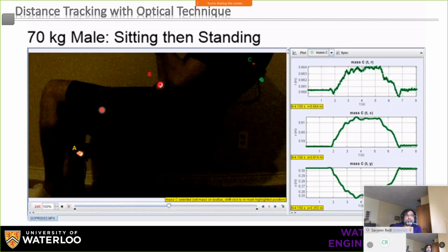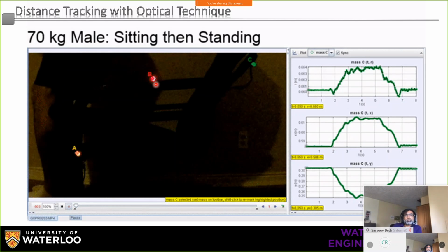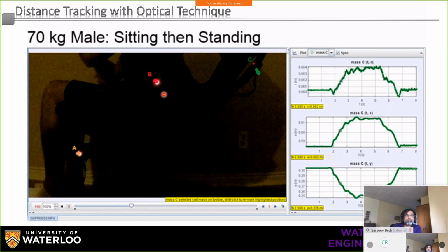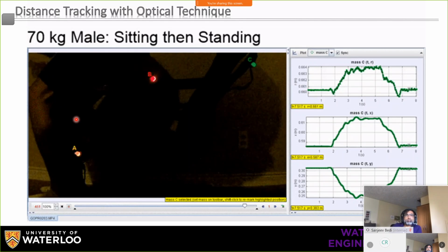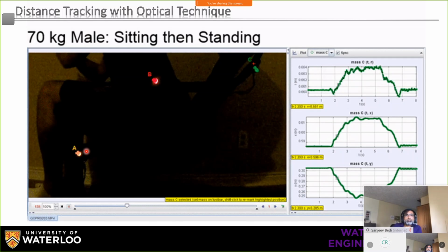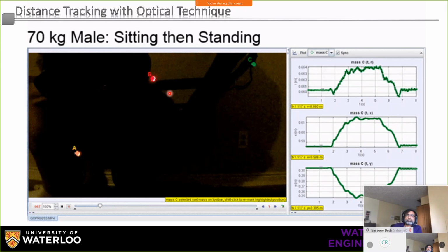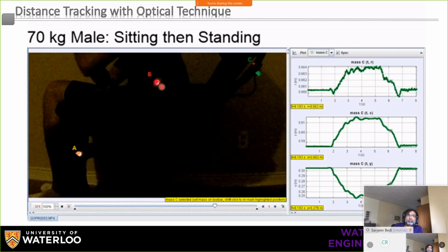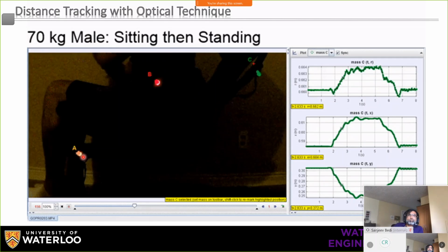We're using a software suite that looks at pixel brightness, tracing pixel brightness over time in this video. And once we give it some dimensions in terms of pixels, say the distance between A and C, we can calibrate the distance based on the CAD model exactly. Once it knows how many pixels each of these points is moving, it can convert that into a distance. And why is this important? Well, we can see that point A isn't really moving very much, as one might expect.